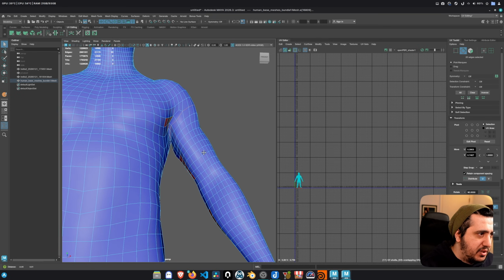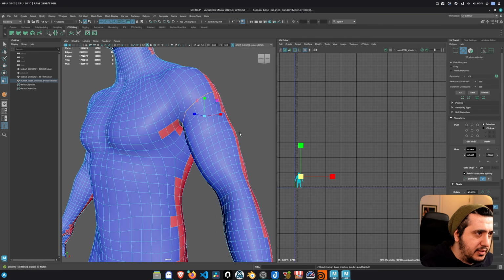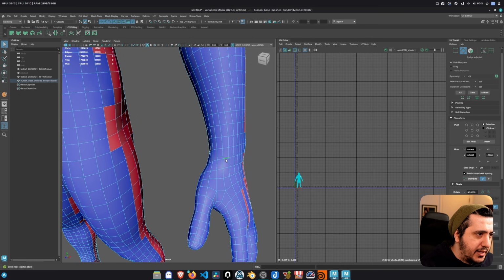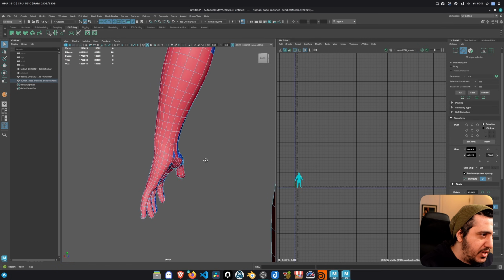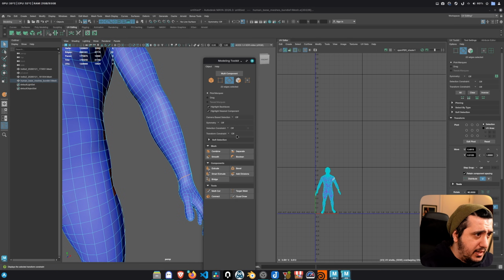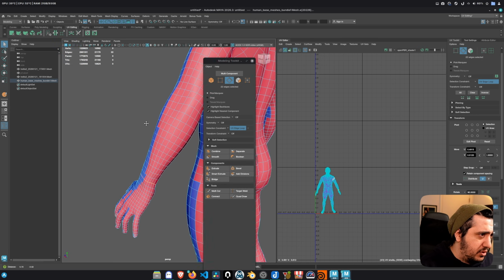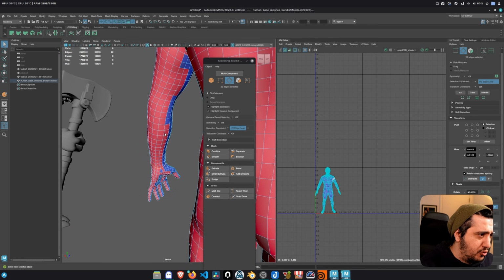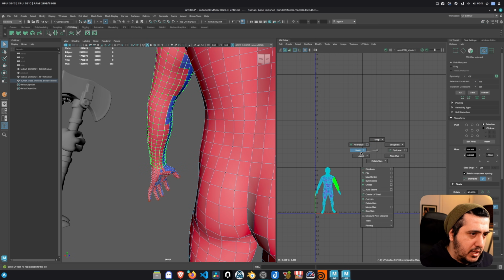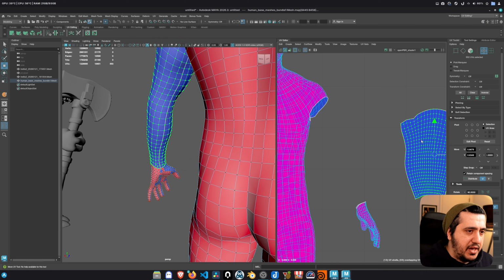So for example, this is an edge loop. I can cut this from here, and I can cut this maybe from here, okay? And then I can get my selection constraints, UV edge loop. This is a tool that is going to give me an edge loop between those cuts. I can select this cut. Now I can unwrap this in a very nice way.